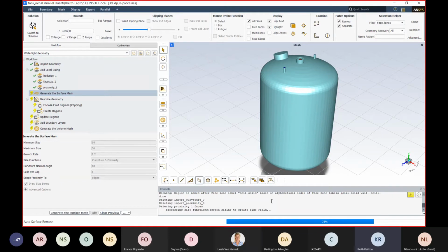If you move over to polys and polyhex core, you're looking at about 6 gigs of RAM per million cells. But there is a trade-off, because for the number of cells required, your tets always need more than your polyhex core mesh or your poly mesh. So they use similar amounts of RAM for a particular size. For tets it's about 1-2 gigs of RAM per million, whereas for your hex and poly it's about 6 gigs per million.